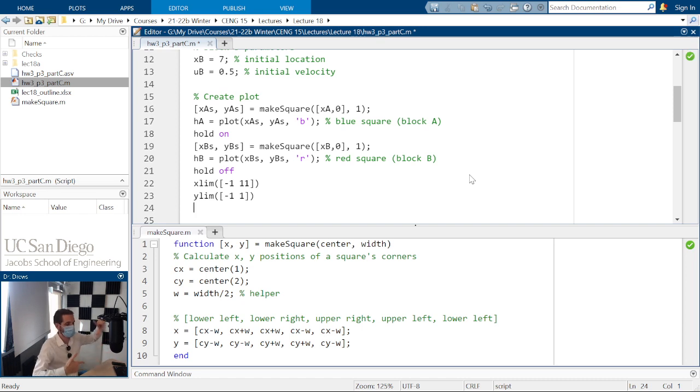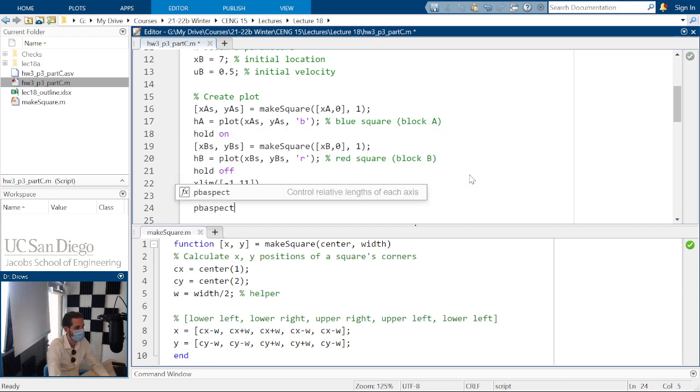And then so that the thing actually looks square, because if we try to plot that, MATLAB is going to try to force the aspect ratio to be square. We can say pbaspect, and if I have 2 units in one direction and 12 in the other, I can set this to something like 2 and 12. The 1 is always just along for the ride because it's X, Y, and Z. That will scale it to what we think looks like a square.